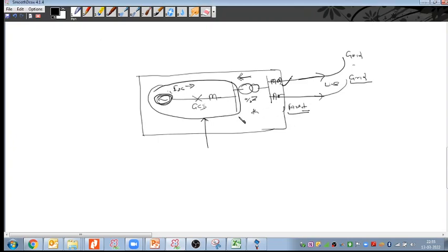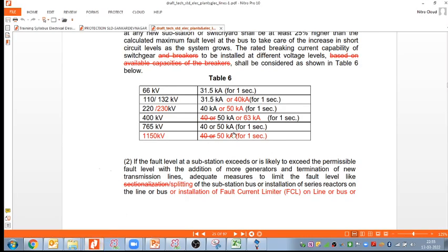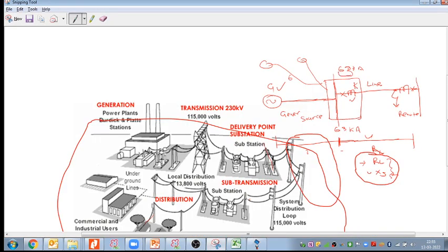They are telling that when we are doing the CT sizing, how do we find out which short circuit current we have to take, like the IK max value. The IK max value of 63 kiloampere we are taking from the CEA for that kilovolt level, so that voltage we are directly taking here, 63 kiloampere.